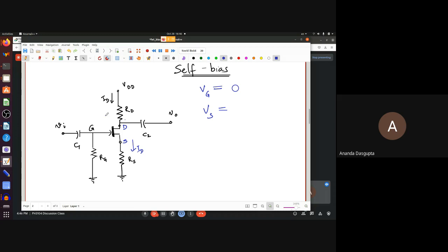There is no way current can go through this, which actually makes analyzing FET circuits way easier than BJT circuits, because in BJT, you have all 3 currents. Of course, there you have to say that the emitter current has to be base current plus collector current. That's Kirchhoff's current law there. Here, Kirchhoff's current law would simply be ID goes in, what goes out has to be ID.